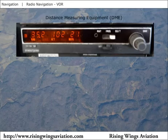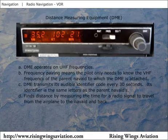DME, or distance measuring equipment, consists of stations on the ground and equipment in the airplane. DME operates in the ultra-high frequency, or UHF, band of frequencies. When a VOR is fitted with DME equipment, it is referred to as a VOR/DME. Each VHF VOR frequency is paired with a specific UHF DME frequency. This means the pilot only needs to use the VOR frequency and does not need to be concerned with the DME's UHF frequency.